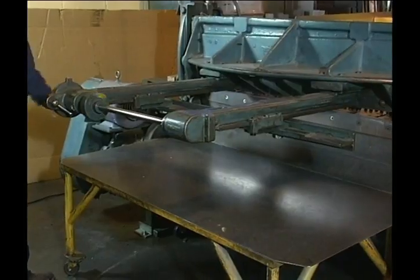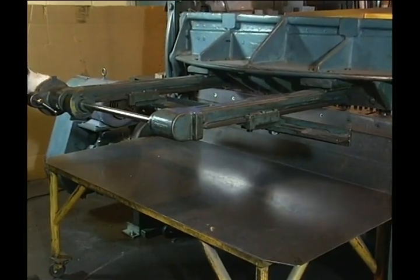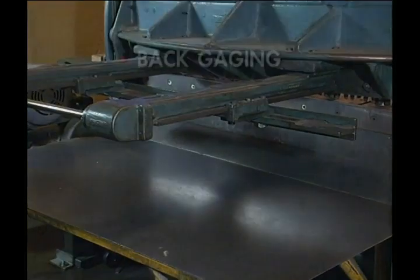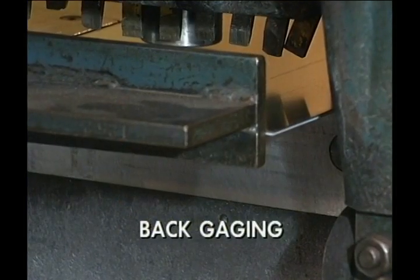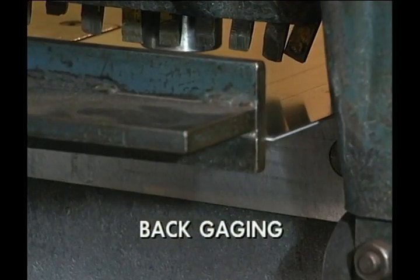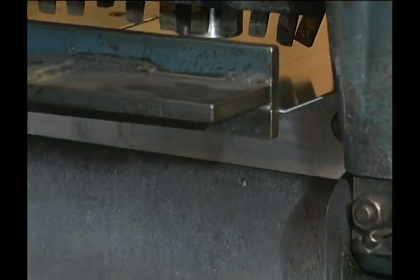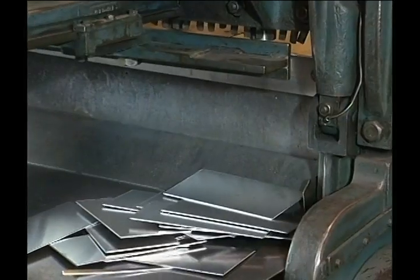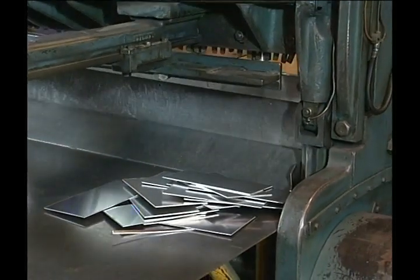Shears must have some kind of gauge for measuring the part to be sheared. Four primary methods of gauging include back gauging, front gauging, squaring arm gauging, and programmable gauging that can operate under computer numerical control. In back gauging, the operator pushes the material between the knives until it comes to rest against an adjustable stop or back gauge. The material is then sheared.